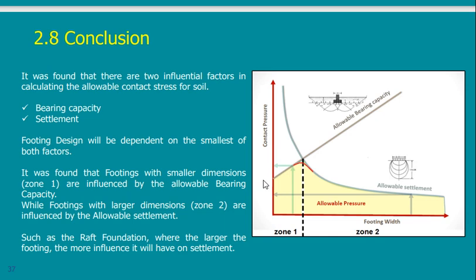If not, then I have to recheck at once. After this recheck, I will end up with a number that matches my assumption. It's called iteration. Usually you do 2 iterations, 3 iterations maximum to reach a very exact design.